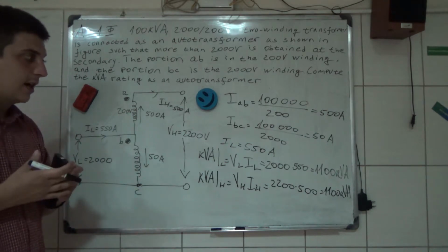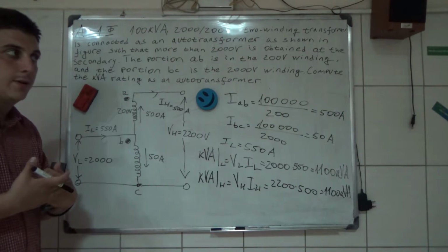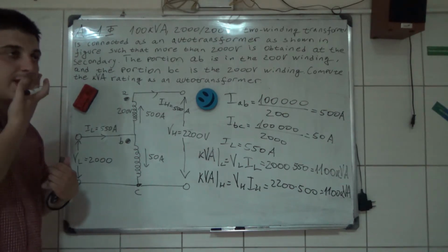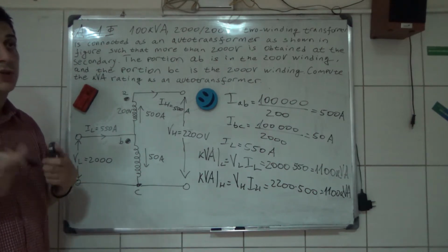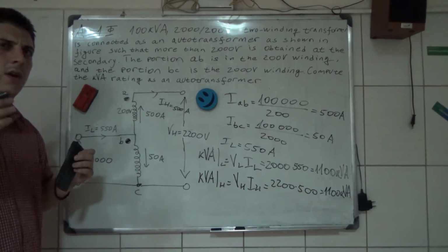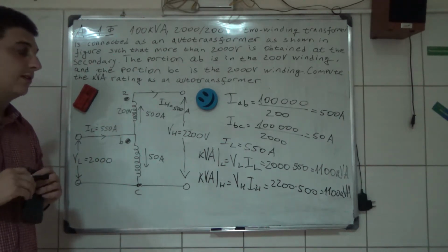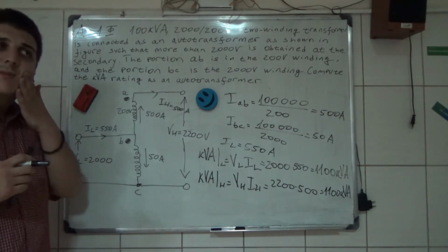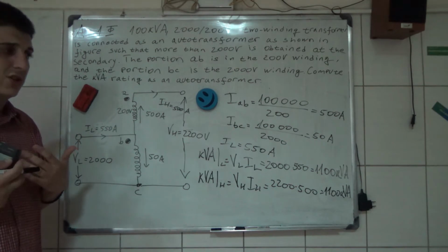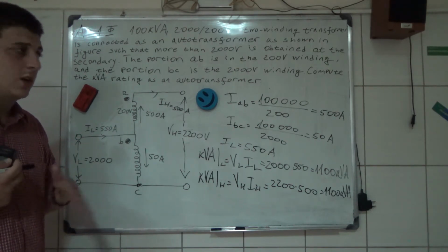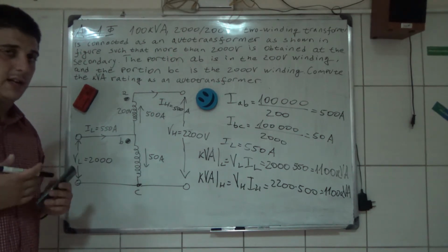So as an auto transformer, you can transfer more power to the output if you step up the voltage in this particular situation. Auto transformers also have lower internal resistances and heating problems than the single phase transformer. But the biggest problem is if you need electrical insulation, then you cannot use a single phase transformer as an auto transformer.